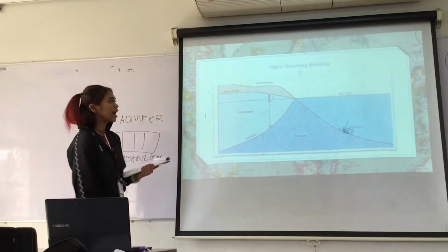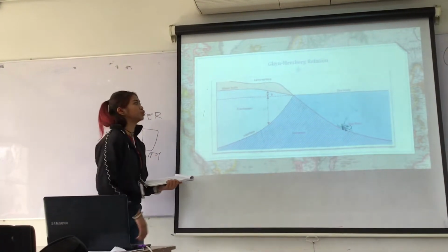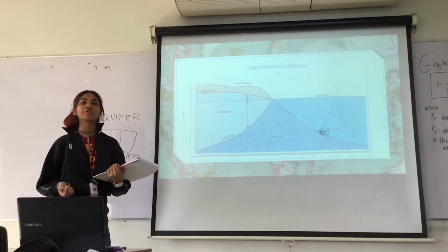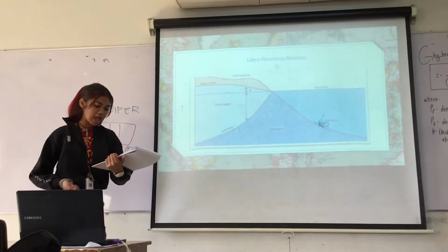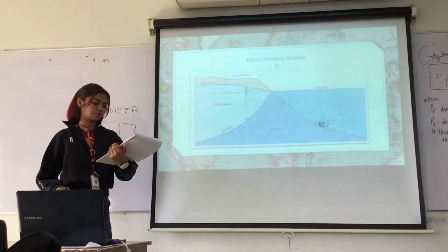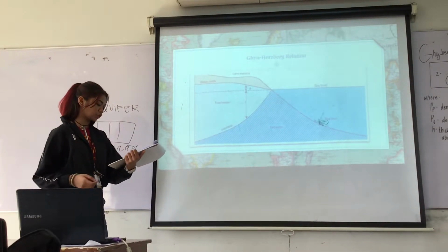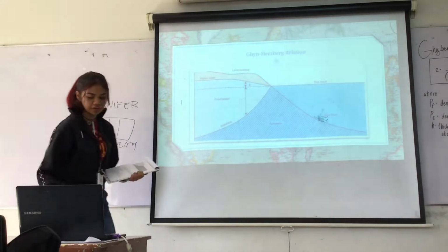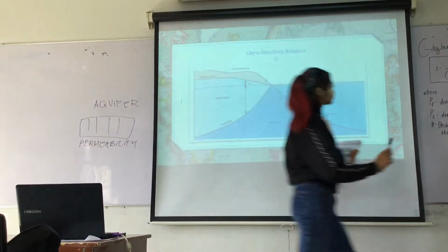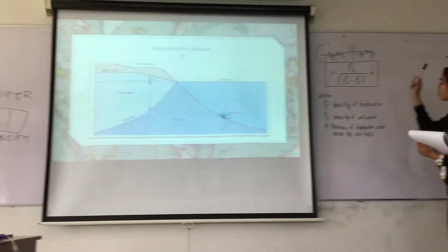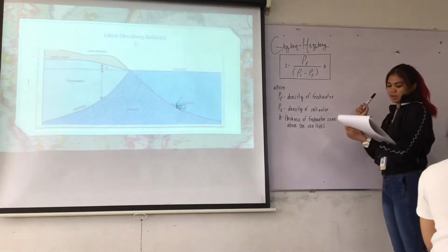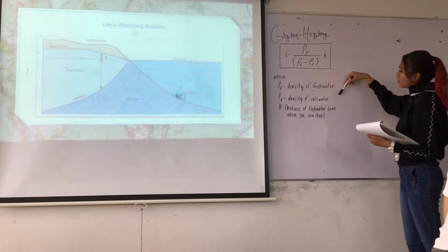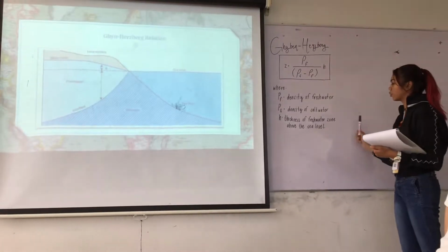Now, to delve deeper into saltwater intrusion, we could use the Ghyben-Herzberg relation. The Ghyben-Herzberg relation is the first physical formulation of saltwater intrusion. They derive analytical solutions to approximate the intrusion behavior, which are based on a number of assumptions that do not hold in all field cases. So the equation entails that Z, where Z is the depth below sea level, ρF is the density of fresh water, ρS is the density of salt water, and h is the thickness of the freshwater zone above sea level.